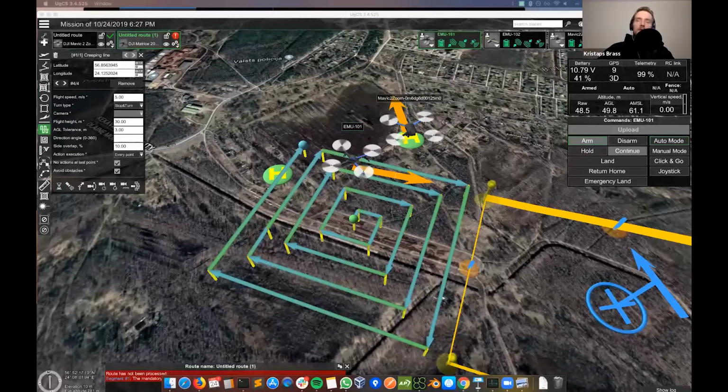And if you already have a DJI drone, so let's say Phantom 4, Mavic, or M200, or some of the other ones, then once you get our app, it's called UgCS for DJI, you can get it from Google Play Store. Then you can go to the main menu, and in the menu you can simply enable the simulator mode. Which I'm actually going to do soon for the M200.